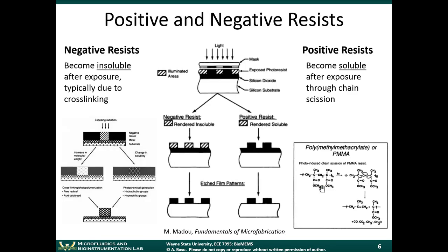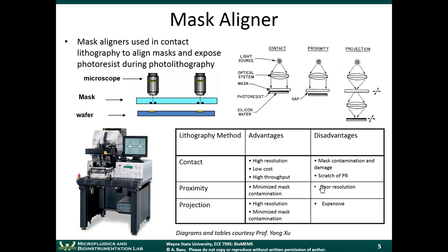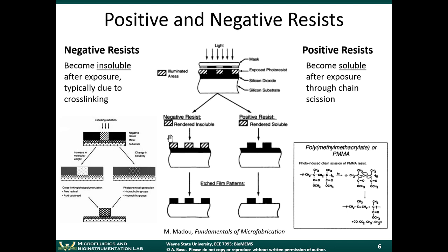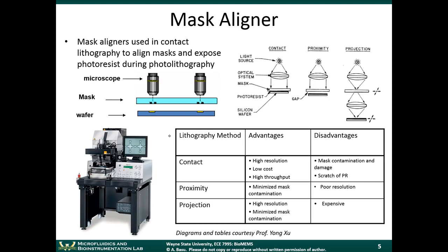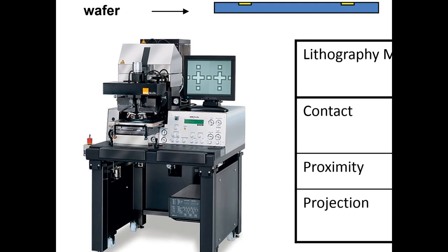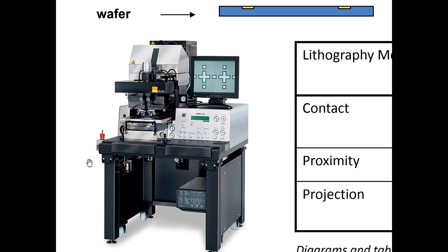So is the majority of that machine really just the alignment portion, not the actual curing? Let's take a look at the different parts of the machine here. So this portion down here is the optics. You can see the 2 microscope objectives. This is where the mask sits. Your silicon wafer is placed under here, and the machine will press the silicon wafer up against the mask.